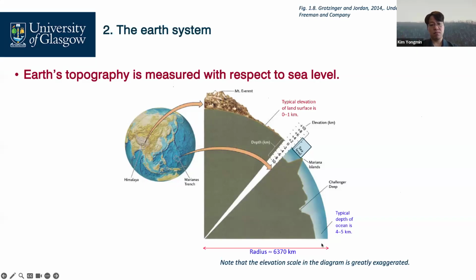But it is a bit of a different story in the geotechnical engineering field. The elevation is typically set based on the ground surface, not the mean sea level. When you take a look at borehole logs and borehole data, the next time you can see it.